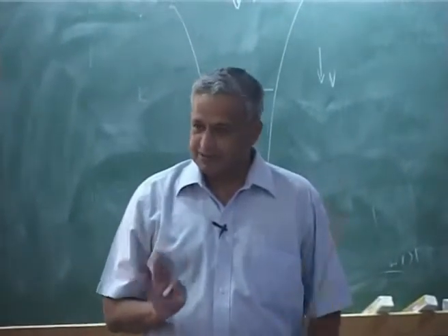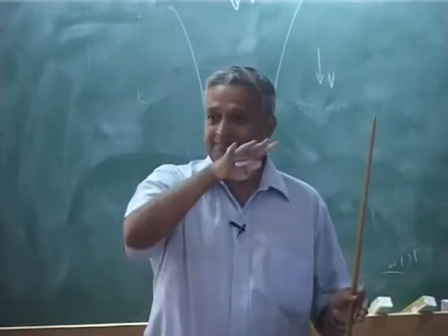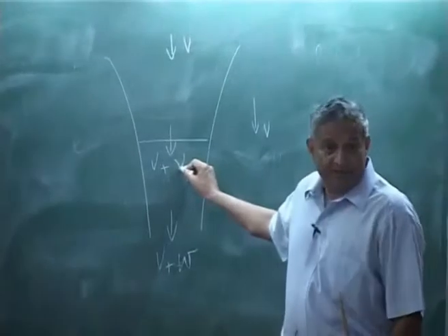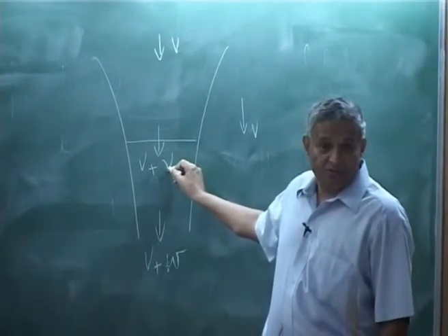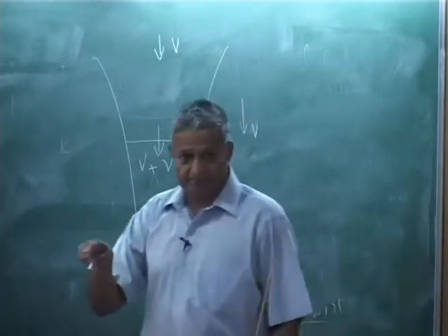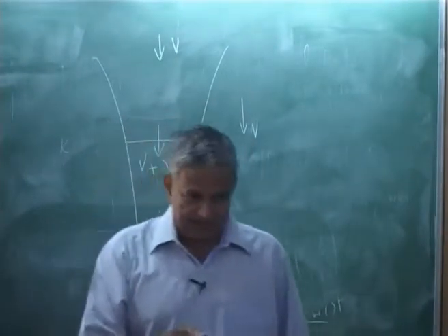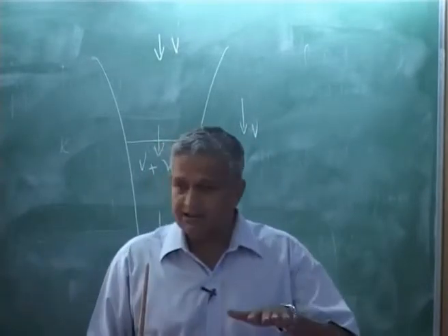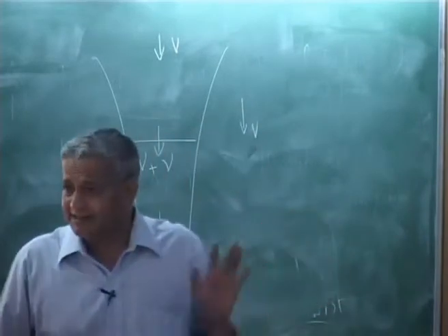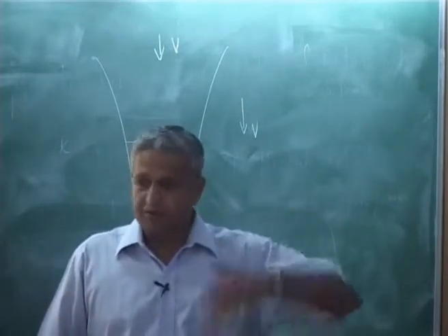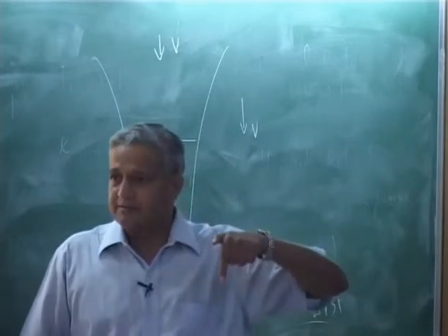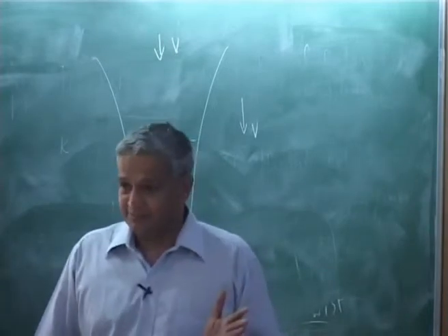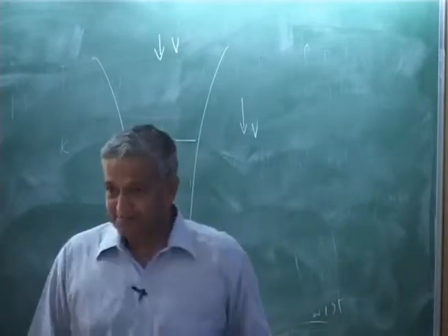So, this is the first part when you are climbing, but the only thing is the value of nu may vary, because this is not the value at hover. The induced velocity will vary depending on flight condition. In hover, it will be root of Ct over 2 lambda I, that is the hover condition. But once you are climbing, the inflow nu over omega r is a different value. For that you will get an expression after this.